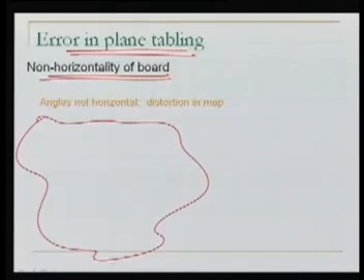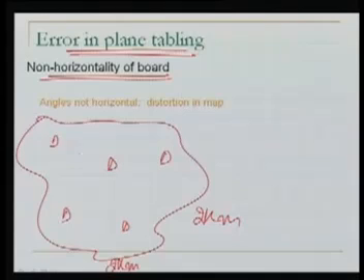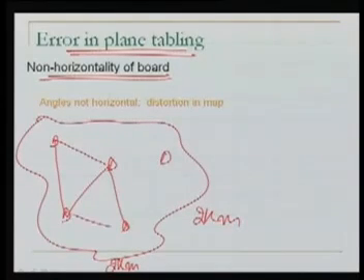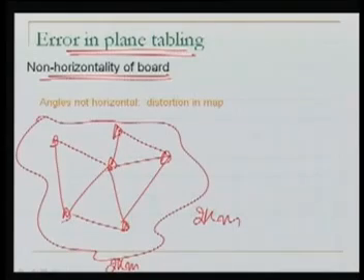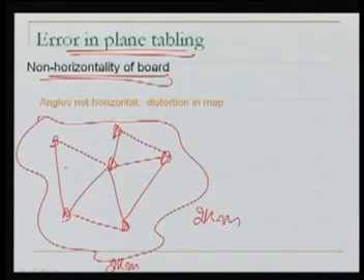Similarly, over here my table is horizontal and I have done the plotting. The next time I take the table to some other place, my table is not horizontal there. So these two maps will not be compatible. One very interesting thing about the plane table is, as we discussed, for a large area, say an area of 2 km by 2 km, we had that control point. Now using this control point, you go into the field with the plane table. We can send different people with the plane table. Let's say this is one party. Over here, there is another party.